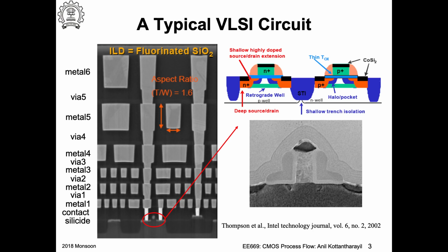Okay, on the right hand side, you have a blown up image of the transistor, and where you can see the right hand side bottom cross section TEM image, transistor with silicon at the bottom, right? And then you have source drain on the left and right ends of this, and then you see these L-shaped features. These are the spacers, and between the spacers come the gate.